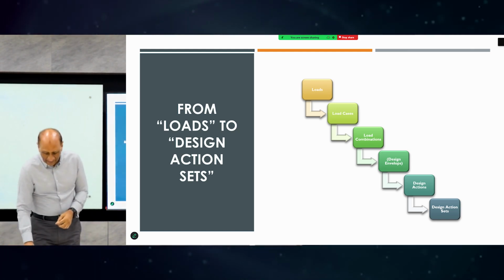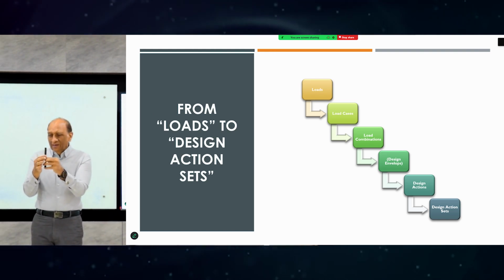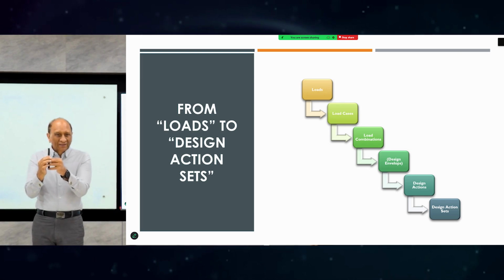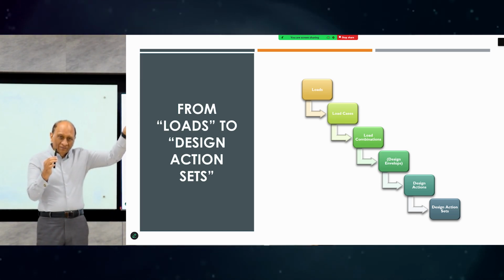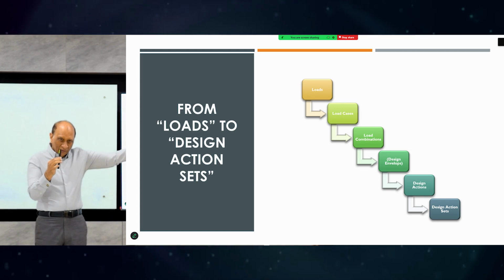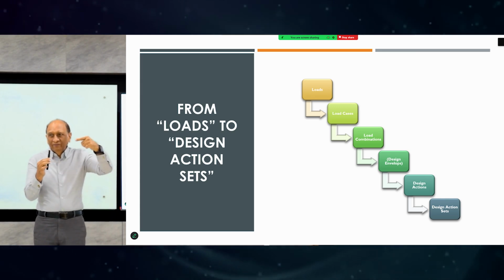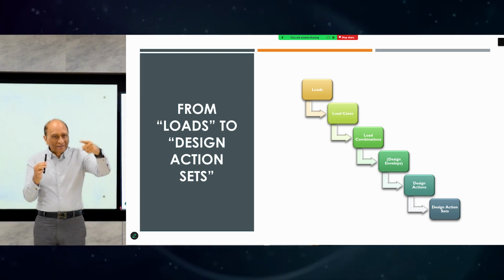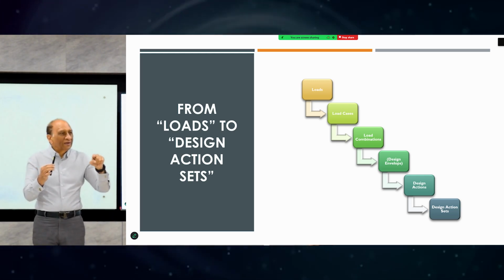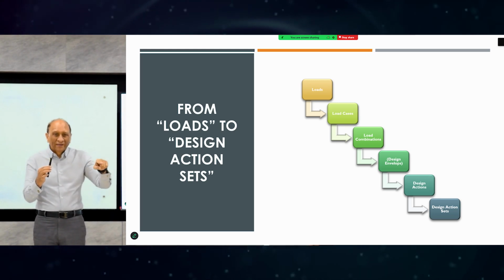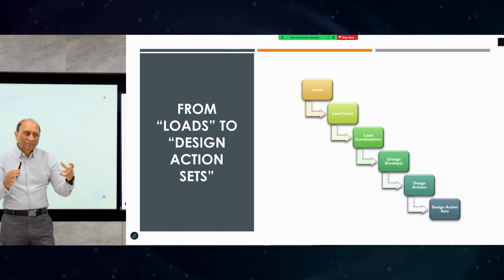So for example, let's say I have a beam column here, and I get some reinforcement in the column. To trace the path, where did this reinforcement come from, you have to see what was the dead load, live load, wind load, earthquake load. Then, what combinations were used. I can combine live load and dead load, and I can combine live load, dead load with wind load, and I can combine dead load and live load with earthquake load, but I cannot combine dead load, live load, and earthquake and wind together, because that combination is unlikely, except for Chinese. People don't consider that.